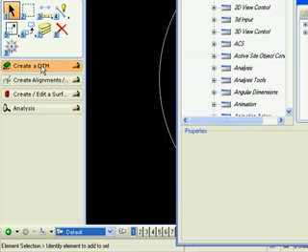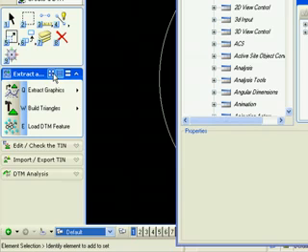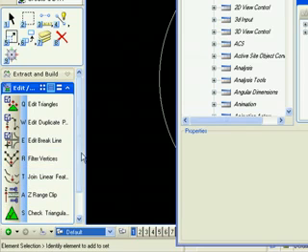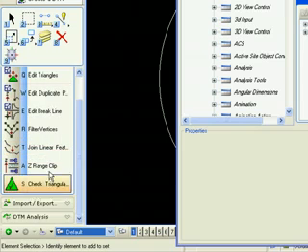If we go into, let's say, create a DTM, and we change it from the icon layout mode to the list layout mode, I can see my task is essentially 3 steps: extract graphics, build triangles, and load my DTM feature. Obviously, there's more tools available to us in our DTM application than those. But for the task of completing a simple DTM, those are all the tools I need. I can then edit or check my tin, again using specific tasks in a specific order.